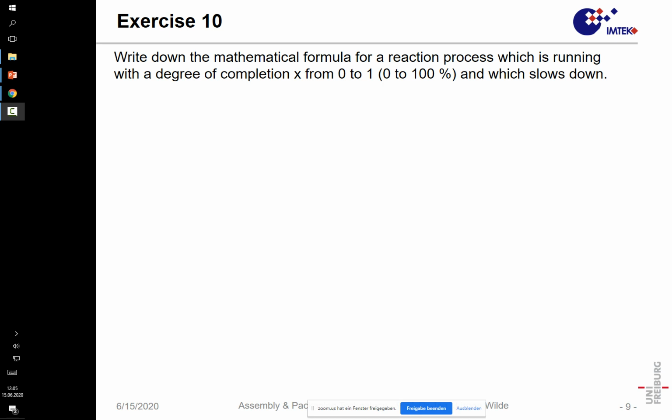prerequisites is that the liquid material will be able to reach the end of the mold so that all lead frames are covered. Another thing is, if it would react too fast, it would harden before the last package has been reached, and also the viscosity of that molding compound would be too high, and that would shear off the bonding wires.